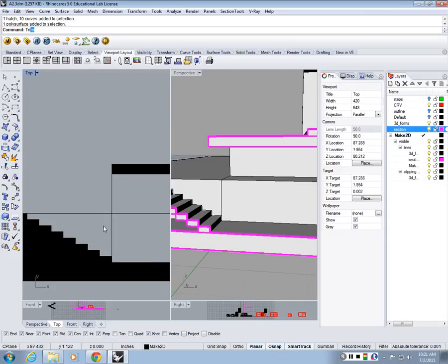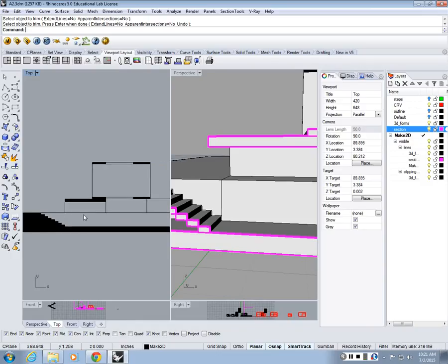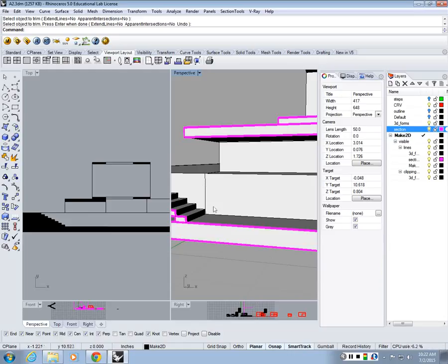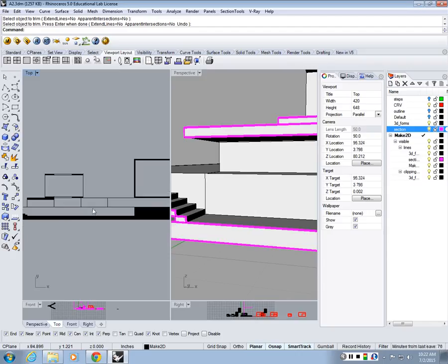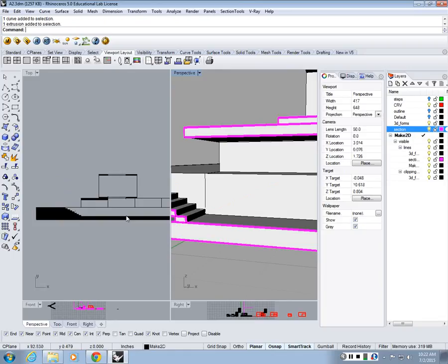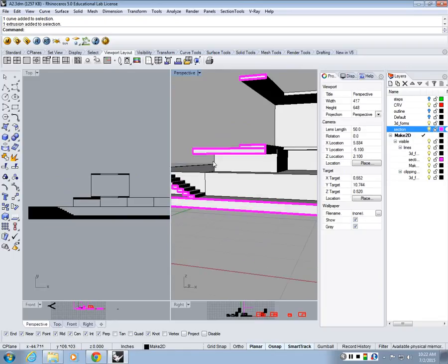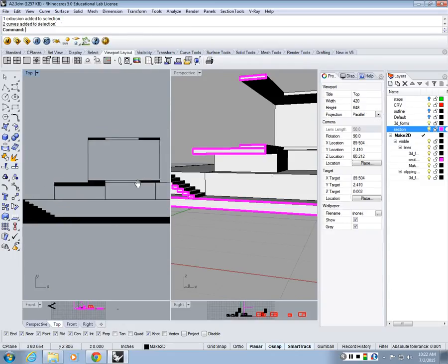So what I need to do is use trim and then get rid of that line, so this reads as a continuous surface, right? That's the same thing you will have to do if your model is stacked. So I want you to come down here, and if you have 8 things stacking up here, you need to delete them and make them into one single wall line, right? So it looks clean. So this guy is this wall basically, and then these 2 lines come from these 2, right?